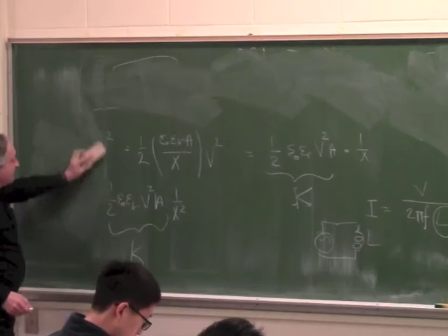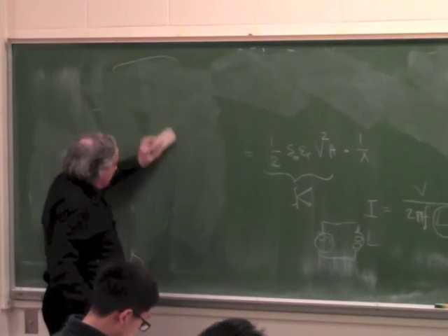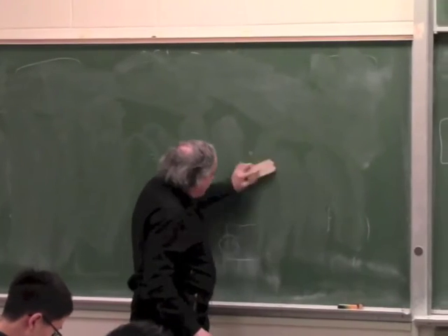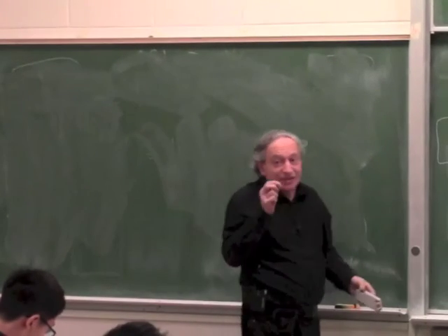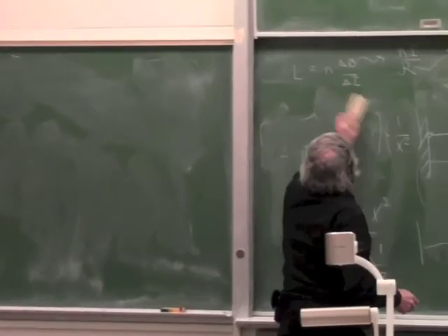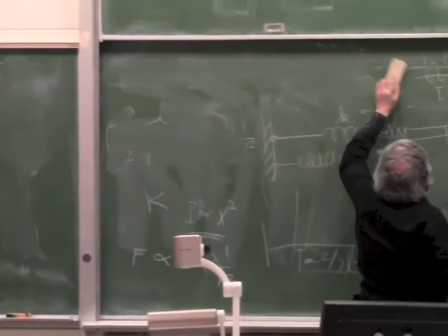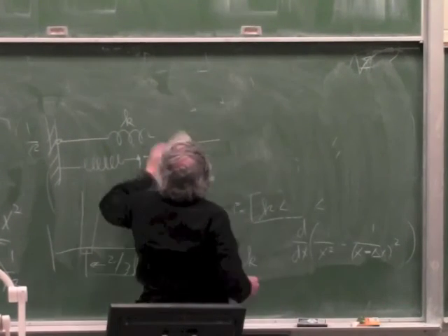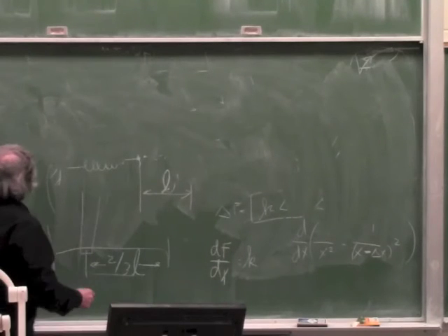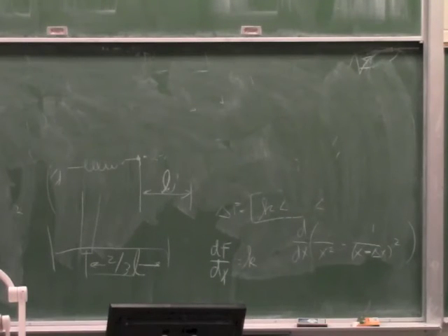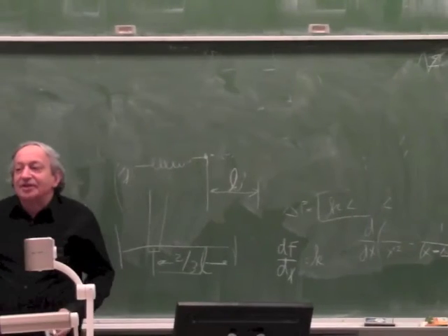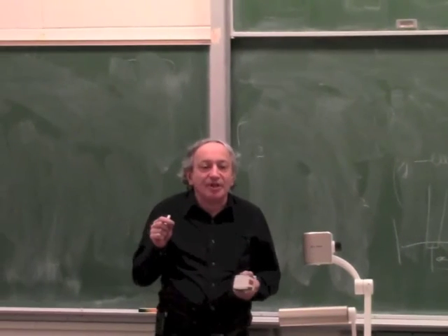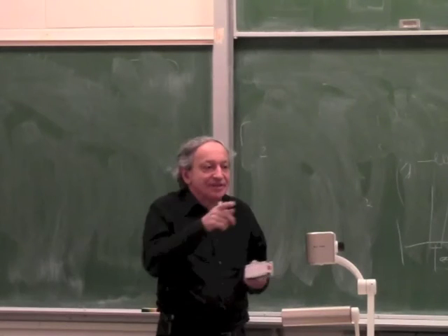So I also mentioned in the last lecture that a very common actuator today is actually electrostatic, although it can have very small forces. The reason the electrostatic actuator became common is that it's very good for MEMS, because you don't have to make coils. Also, when the gap is very small and the actuator is very small, the electrostatic forces are comparable to electromagnetic forces.